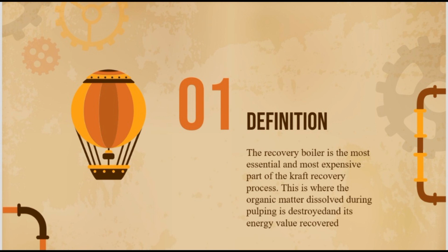The recovery boilers consist of a water-walled furnace where black liquor combustion is completed, followed by a series of heat transfer surfaces where hot combustion gases are cooled and superheated steam is produced.